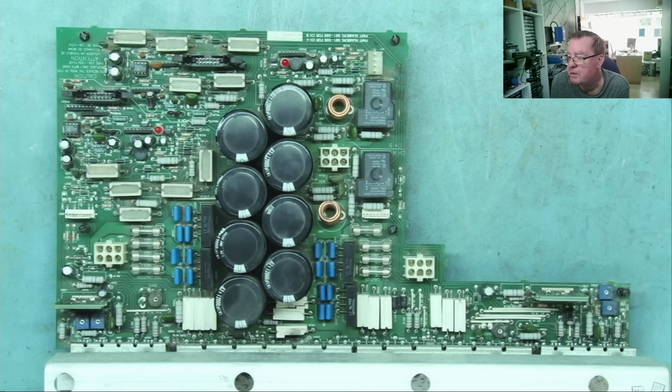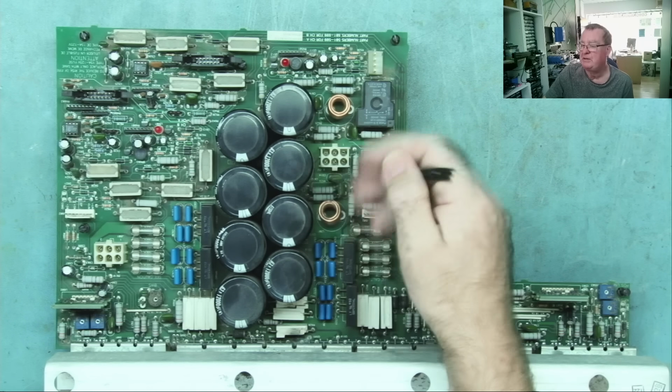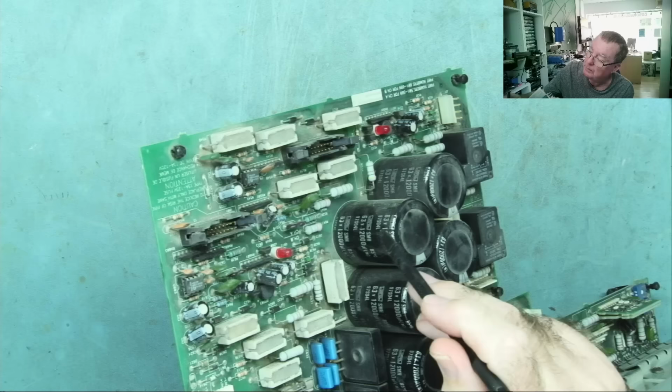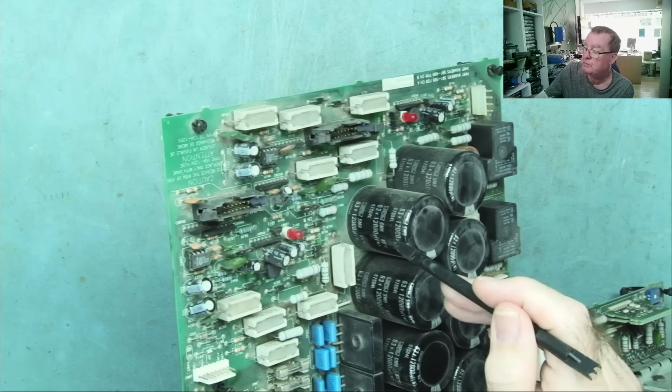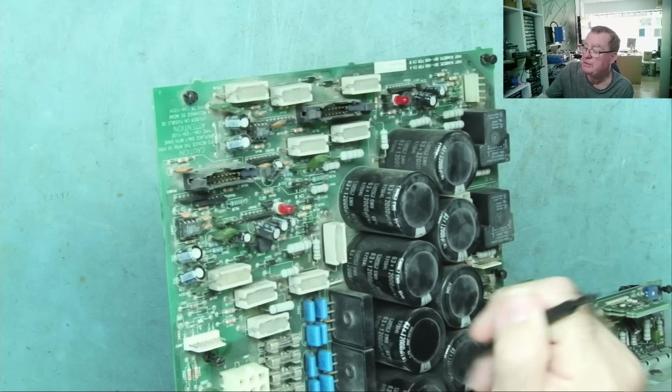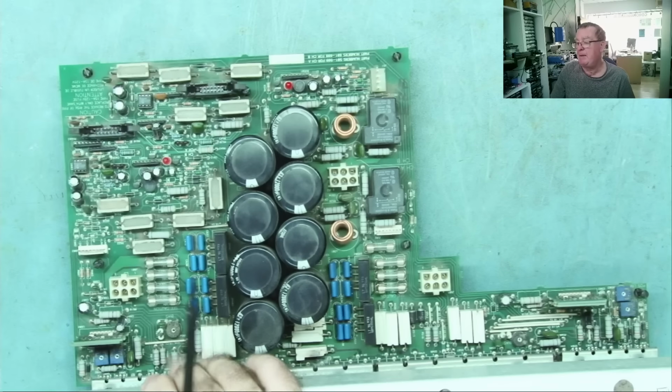So when it comes to capacitors and failures, apart from the capacitor plague, some important factors are A, the type of capacitor that we're talking about, B, the working voltage and specifically how close to its maximum it is being pushed in the device, and thirdly, the frequency that they are working on. So large capacitors like these you'll find in amplifiers, for example, but also in pretty much all mains powered equipment. These are 63 volts, 12,000 microfarads, and these are smoothing the input voltage.